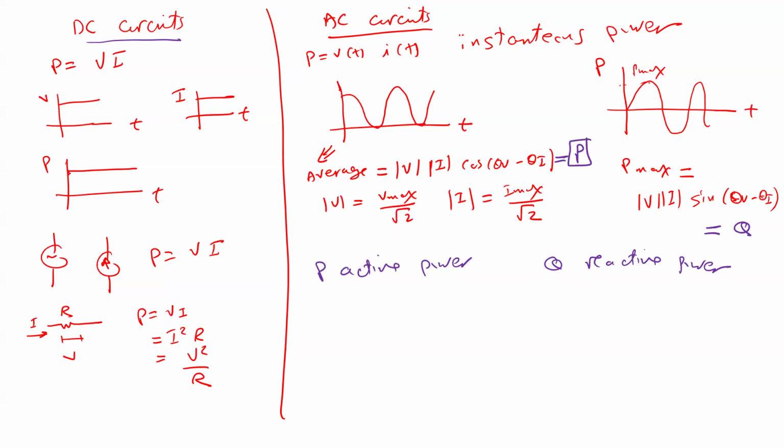If it is a resistance, you can calculate the power in the resistance in three different ways. V times I, where V is the voltage drop across the resistance, or I squared R, or V squared divided by R. The three ways give you the same result. Here we also explain power conservation, which means the amount of power generated by the sources should equal the amount of power consumed by the resistance.